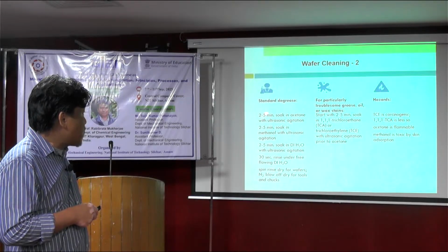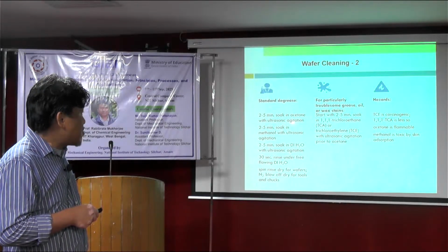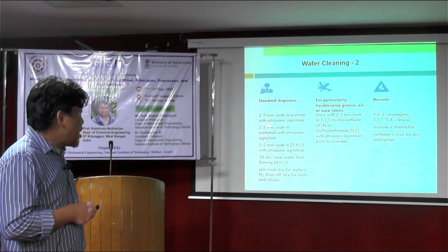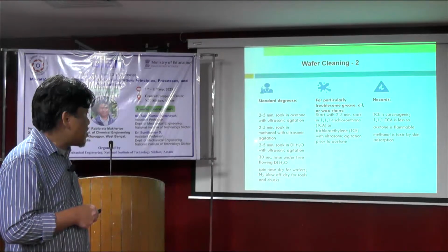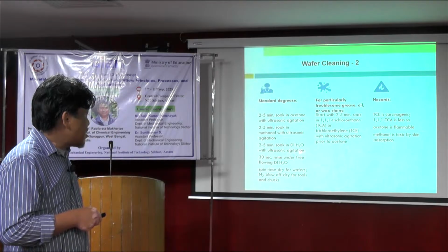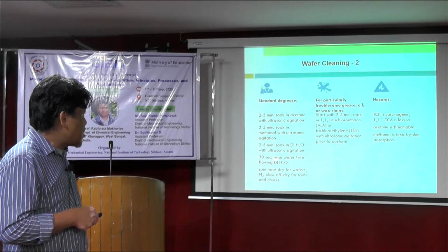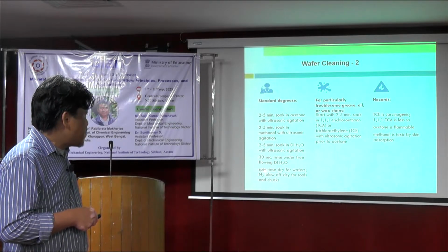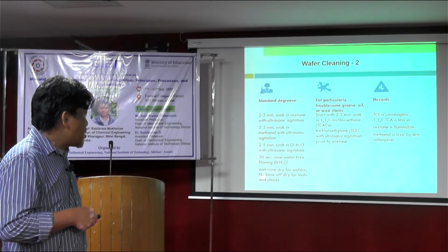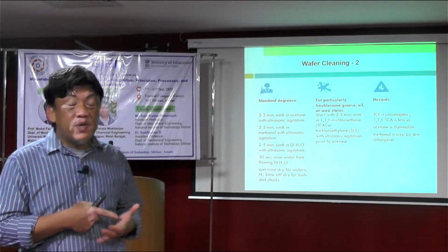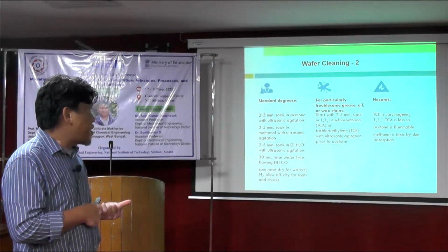The process is 2 to 5 minutes soaked in acetone with ultrasonic agitation, so an ultrasonic cleaning process, and 2 to 5 minutes soaked in methanol with ultrasonic agitation, and 2 to 5 minutes soaked in DI water with ultrasonic as well, and a 30-second rinse under free flowing DI water, and spin rinse dry for wafers, and a nitrogen blow off for tools and chucks. So we normally use nitrogen in the clean room to blow the air or to clean the surface.